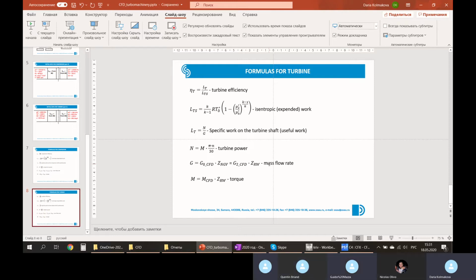So, any questions about post-processing turbine results? No, it's clear. Do we need, the mass flow should respect the continuity. So the mass flow at the inlet should be the same as the outlet. If it's not so, there is a problem, right? Yes. Right.